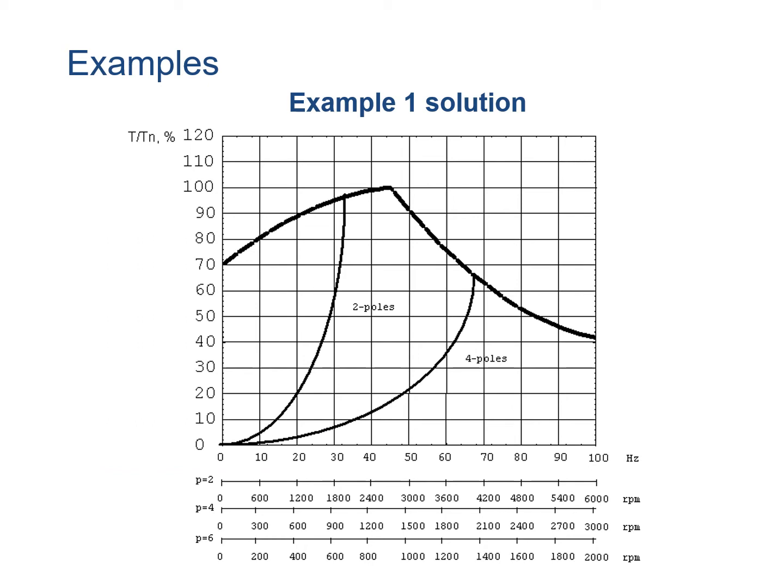So now we see the chart, which may look from the first glance a little bit too complicated, but I will explain what is here. If we try to choose or to use a two-pole motor, 3000 RPM motor for driving our pump, then we are here on this line. So 2000 RPM will be somewhere here, and this is where we put the operational point of our pump. So our system should then have the torque not lower, at least, than this point.